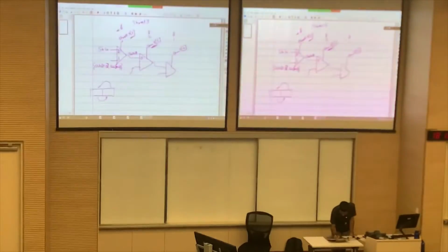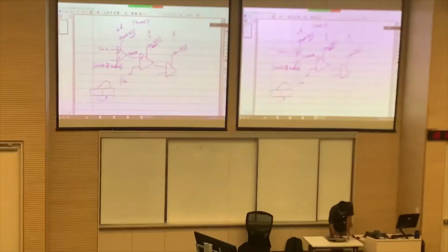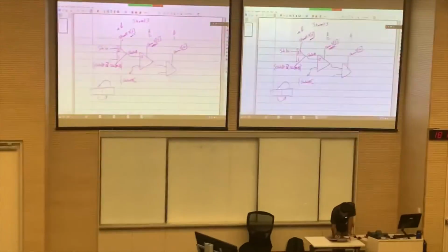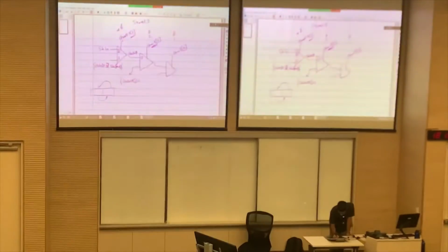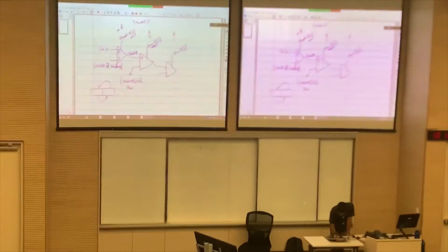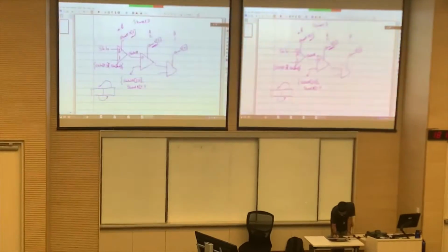Here it will be rotation by an amount of 2. So here what you would have is a right rotation. So what you need to give here is SH out A 1 down to 0, and SH out A 7 down to 2.